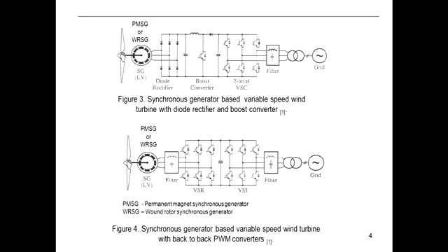Okay, so if you look at the situation in a wind turbine power generating station, this is a small scale system where there is a machine which converts the mechanical motion into electrical energy. The wind incident on the blades lets it rotate, all right? And then the AC produced goes to a capacitor, all right? And you then boost it up to another voltage, because this voltage may be variable and it is normally lower than required to connect directly to the grid. So you boost it up to another level, and then you have a three-phase inverter to connect to the grid.